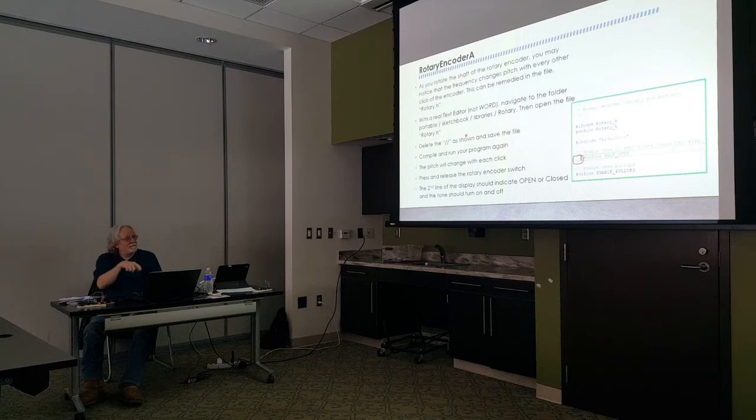you have to go into the header file for the rotary encoder and get rid of those little hash marks right there. What that does is, in the header file, there are two different tables for what the code coming out of the rotary encoder means. And so now when it goes click, tone changes, click, tone changes, click, tone changes.